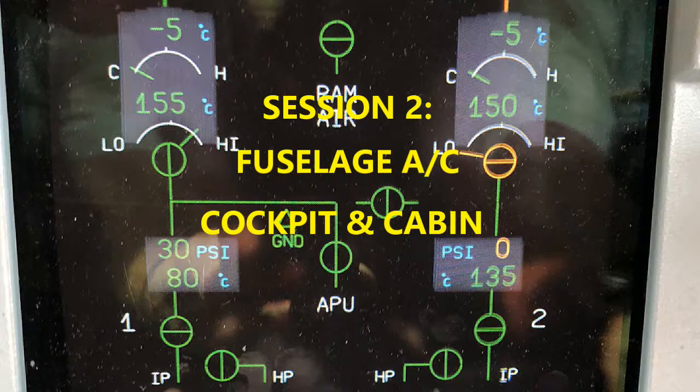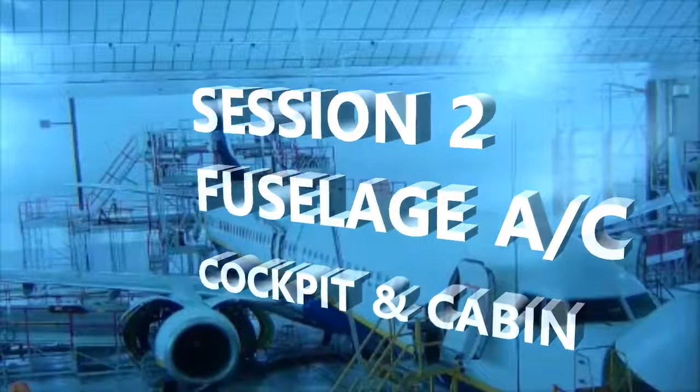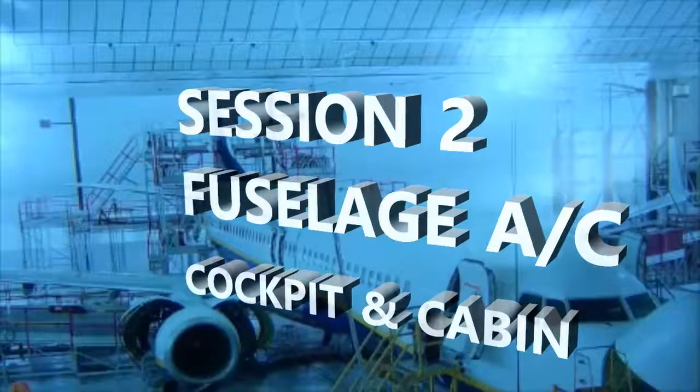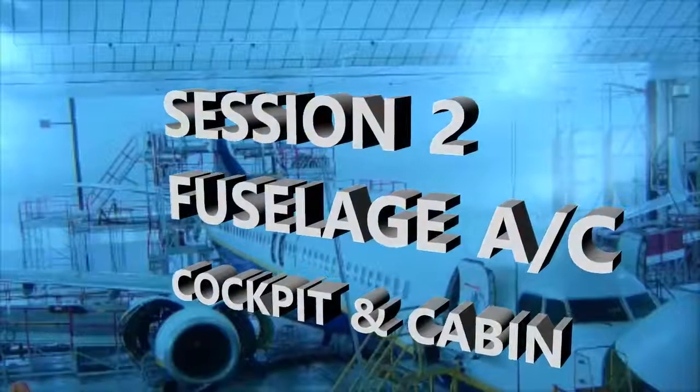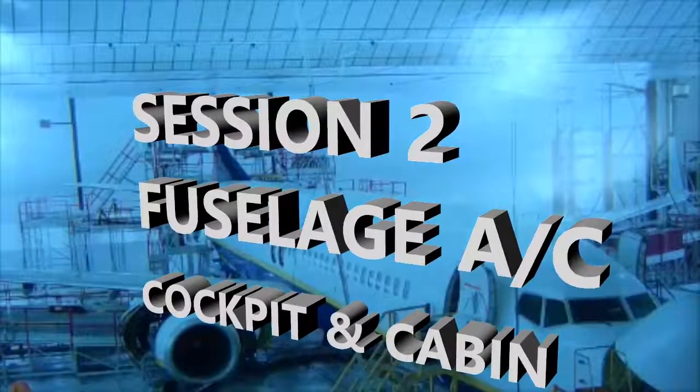I want to go over a little more on the sensors. I briefly mentioned that we have sensors in the ducts and also at the mixing unit, which we'll get into in just a little bit. But here you've got different ones: the compressor discharge temperature sensor, one for the water extractor bleed temperature, and your pack discharge temperature sensor. Those are the different ones you have as part of the pack.